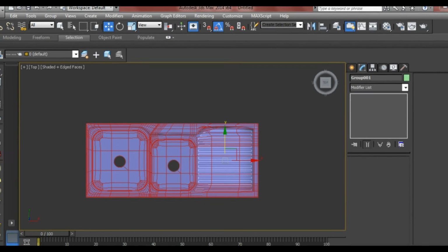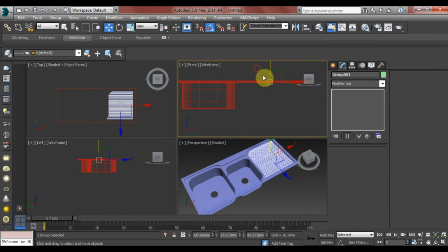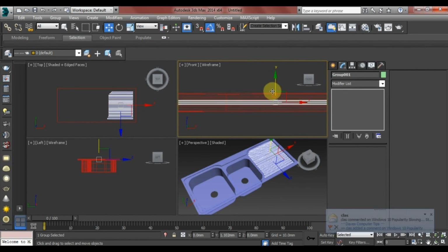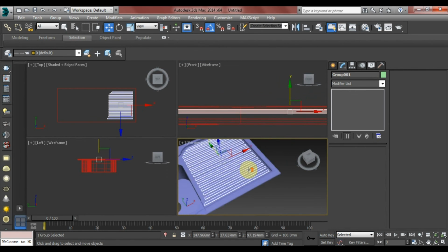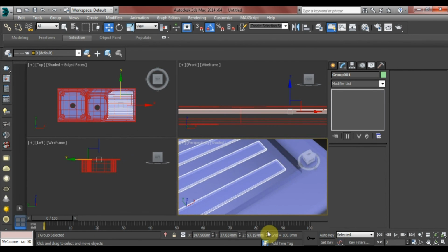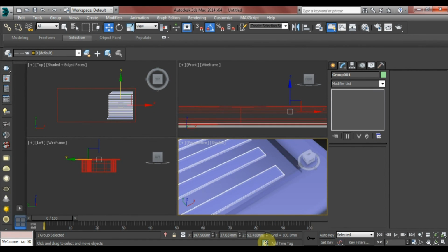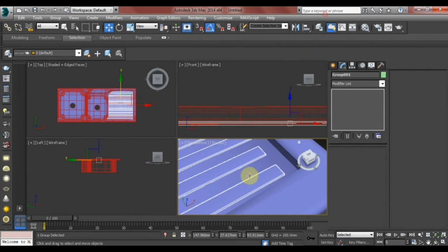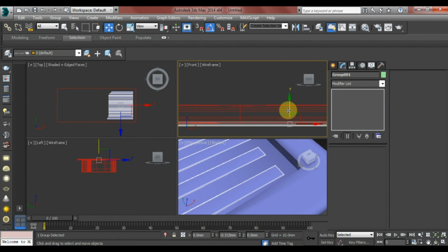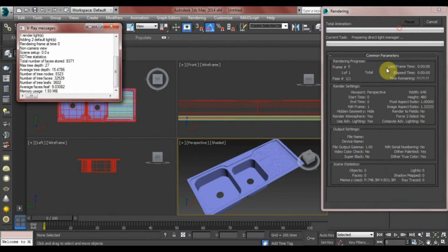Now what we're going to do is get out of that viewport, and we're going to drag up and zoom in, drag up these bars. It should be about right. We can make some fine adjustments with the Z coordinate here, as you can see, and it might be a bit easier if we go back to the material and change that to full opacity. So as you can see, that's sinking down a little bit. So we've got our basic, I was going to render that.